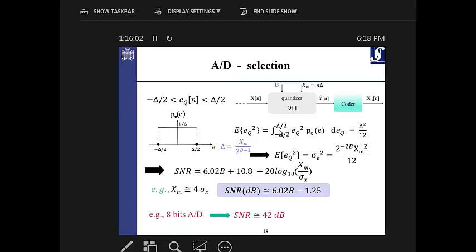So that's the highest, upper limit just because of the quantization level. On the other hand, it's approximately saying that for every single bit that you add to the A to D converter, how much gain will you get? Almost 6 dB gain. Every single bit in the A to D converter will give you almost 6 dB of gain; the upper bound of the signal SNR will increase by 6 dB. Should be 5, right? Sorry? So you subtract 1.25. Yeah, minus 1.25. I said almost.